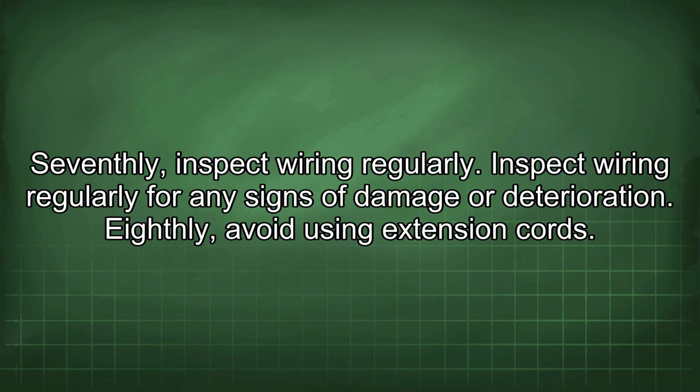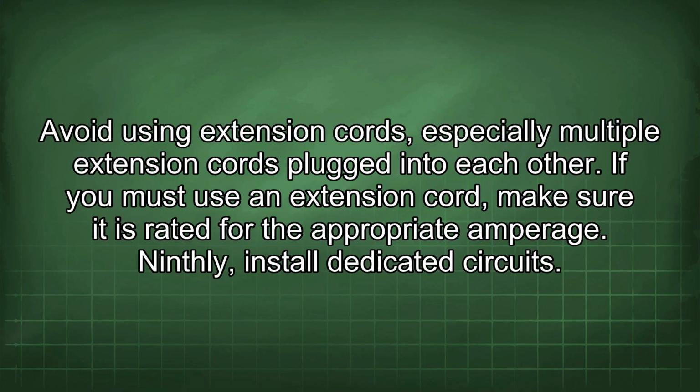Seventhly, inspect wiring regularly. Inspect wiring regularly for any signs of damage or deterioration. Eighthly, avoid using extension cords. Avoid using extension cords, especially multiple extension cords plugged into each other. If you must use an extension cord, make sure it is rated for the appropriate amperage.